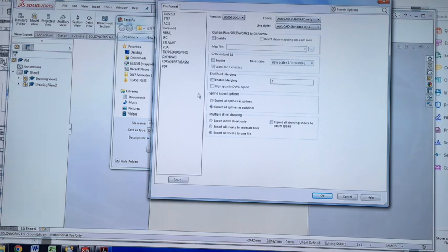Certain tool cutting software that's used with the laser cutters can be quite old, and it won't react well to splines. So it prefers lines as polylines. To save us having to change it all or redraw it in AutoCAD, tick that box there and we should be fine. Press OK.